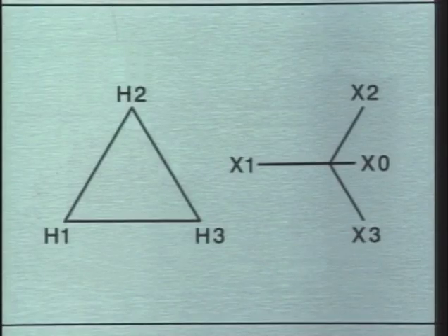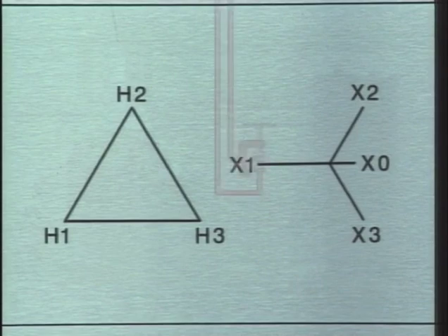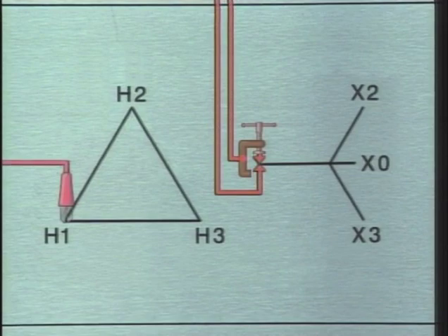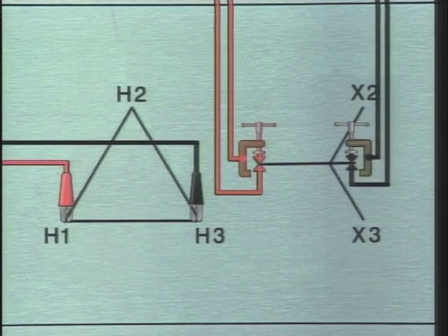The red leads are connected to the higher and lower voltage winding terminals that are at the same ends of the lines on the nameplate connection diagram. For example, the red exciting lead would be connected to terminal X1, and the red high voltage lead would be connected to terminal H1. The black exciting and high voltage leads are connected to the XO and H3 terminals respectively.